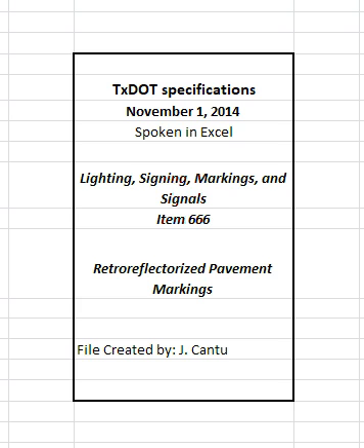Furnish measurements in compliance with special specification, mobile retroreflectivity data collection for pavement markings, unless otherwise approved. The engineer may require an occasional field comparison check with a portable retroreflectometer meeting the requirements listed above to ensure accuracy. Use all equipment in accordance with the manufacturer's recommendations and directions. Inform the engineer at least 24 hours before taking any measurements.